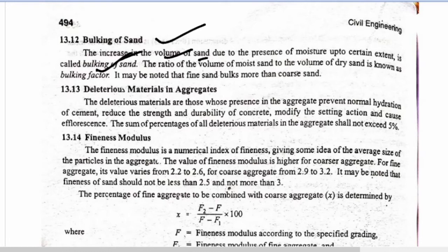The ratio of the volume of moist sand to the volume of dry sand is known as bulking factor. It may be noted that fine sand bulks more than coarse sand. Very very important.